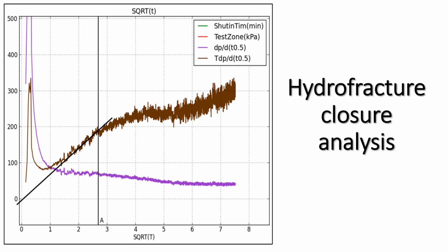Frequently, several sequential fracture closures may be determined. These may be related to fracture rotation or pre-existing fractures within the rock mass closing in sequence. The major stress is difficult to determine from hydrofracture. Most hydrofracture analysis is based upon the axis of the borehole being aligned in the plane of the minimum principal stress. It also relies upon the assumption that the rock behaves in a linearly elastic manner and is homogeneous. These are conditions that are frequently not met.